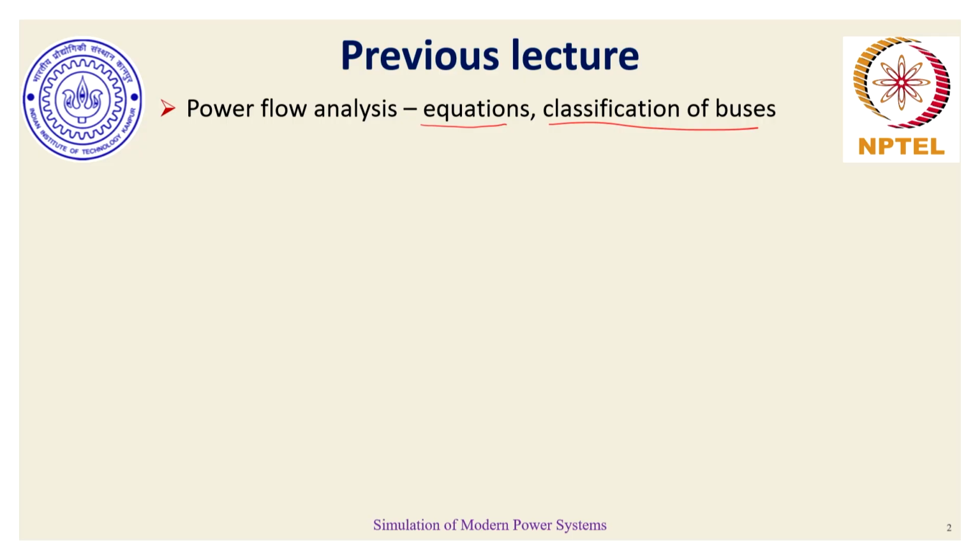What we have seen before I go deep into the discussion is that the power flow equations are nonlinear: transcendental when we choose voltage in polar coordinates, and quadratic when we choose voltages in rectangular coordinates.